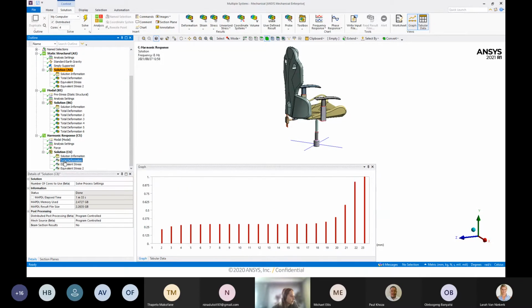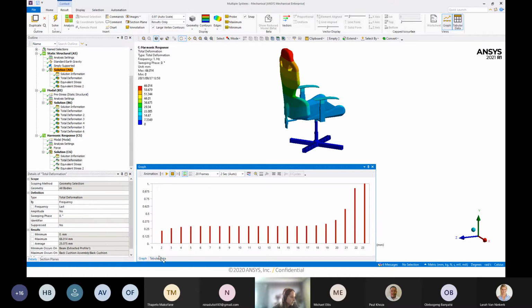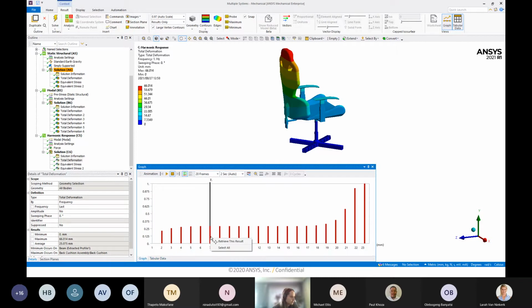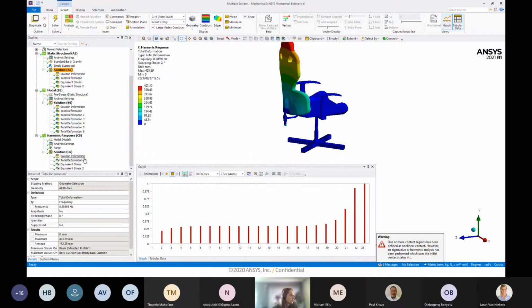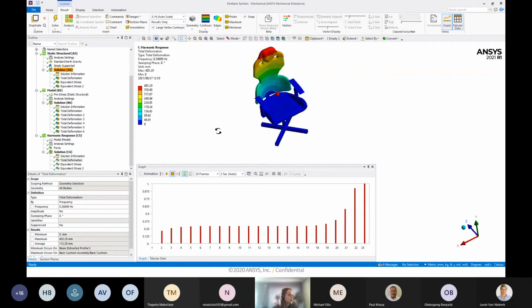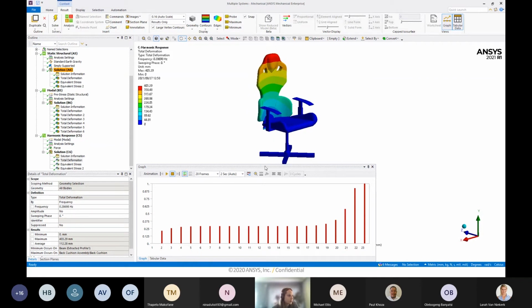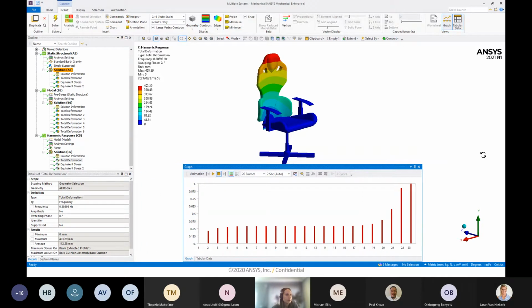Actually, I can just quickly go here and look at which one it was. It clustered the results around the first natural frequency, as I've mentioned, so I can select any of these really. Let's select number 7. Okay, so this should be quite high. Yes, 400. As you can see, the deflection that they give here is 400 millimeters.